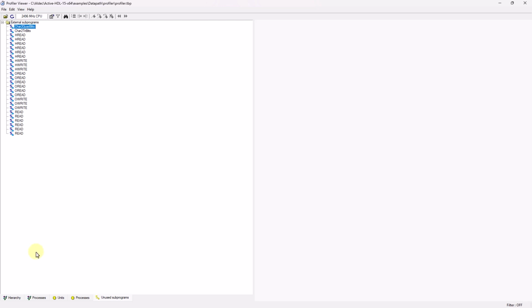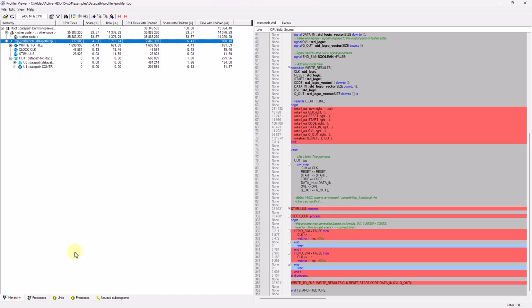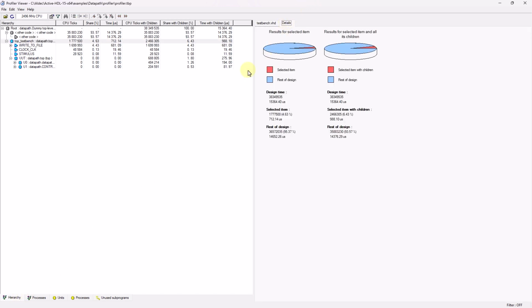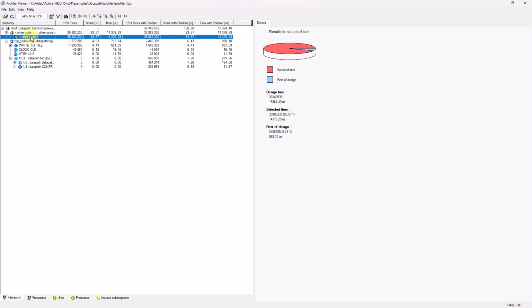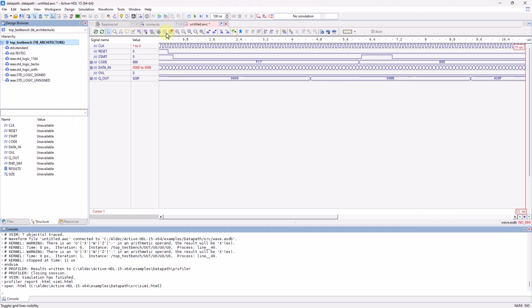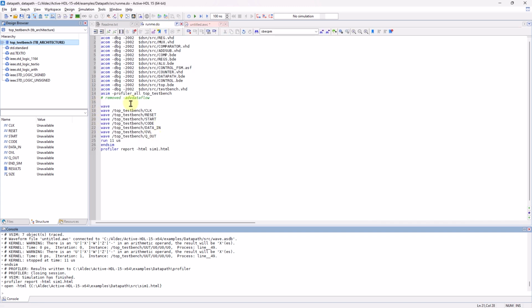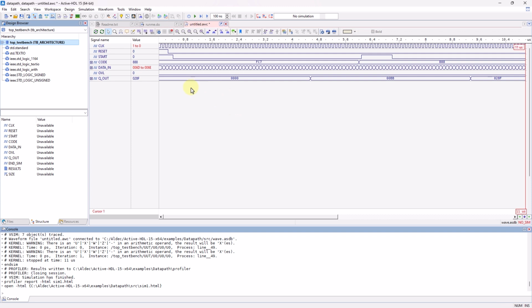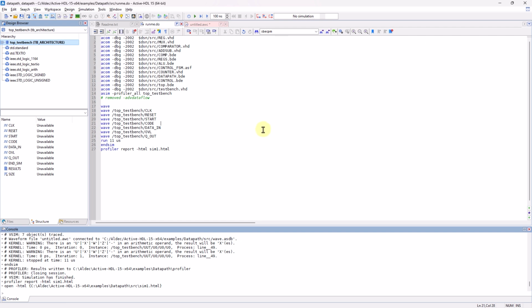As you may have already noticed as early as the HTML report, the other code takes precedence over the actual test bench code because it's taking up a lot of CPU time. This is happening because, if you recall, the macro had commands for the accelerated waveform viewer. During the time that simulation was initialized, waveforms were also being generated for signals. So I'm going to remove some commands to optimize my simulation.